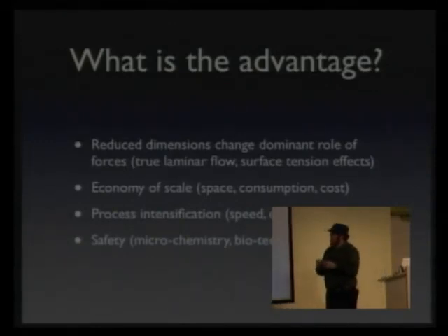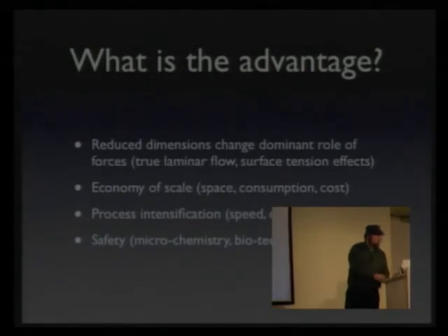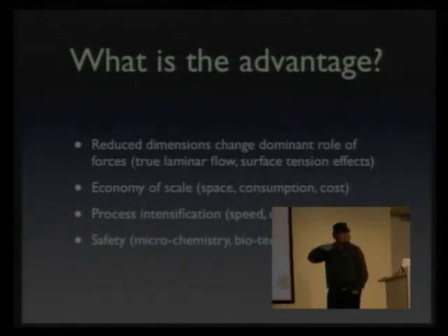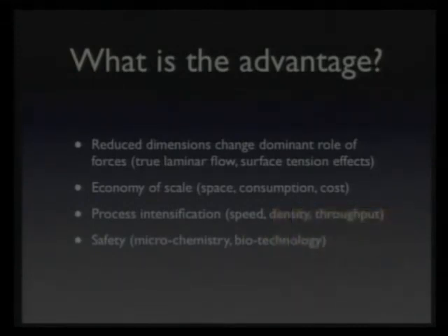with very, very good processes, and they're all batch processes. So you start with a 3-inch wafer, which is about this size, and you get 100 chips on it, or 100 microsystems, and if you just go 1 inch bigger, you can do much more with the same process because it increases over the area by the power of 2. Then basically it's all about, we want to make it safe and cheap.